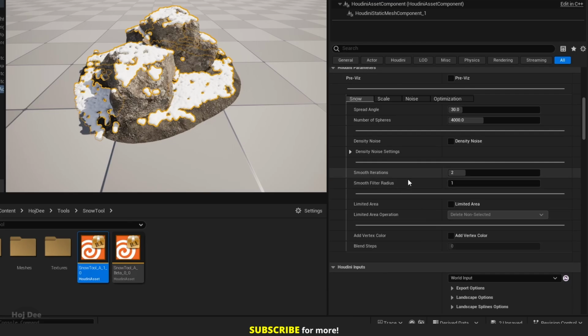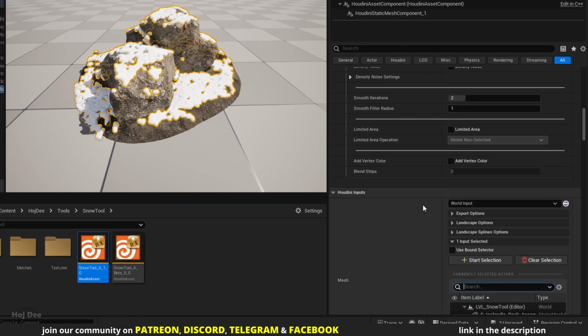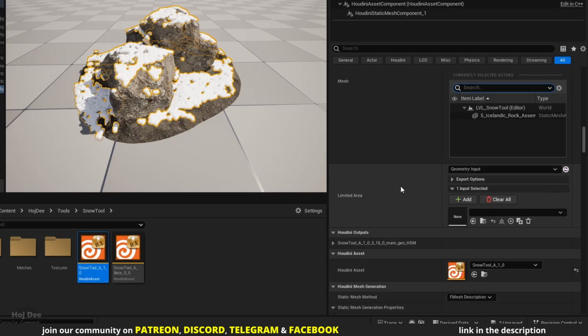These two parameters control the smoothness of the snow mesh. The default values work just fine most of the time, so use them carefully. We can use them if there's something wrong with the snow mesh. Limited area gives us the option to only have snow on specific parts of the mesh. To use it, we should first add a limited area mesh from the input section. So let's scroll down. And here we have the limited area input.